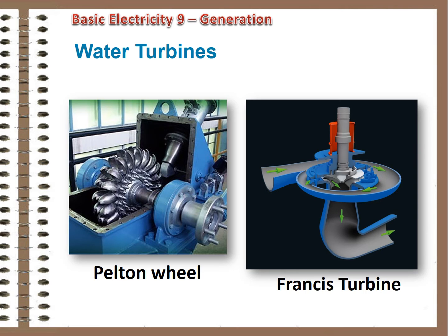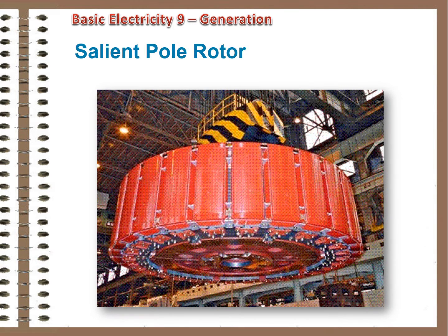Steam-powered AC had no trouble spinning magnets at high enough speeds that the cyclic nature of AC power was not visible. 50 or 60 cycles per second required a rotational speed of 3,000 or 3,600 RPM, easy for a steam turbine. Water wheels can't turn that fast. Their size and bulk made it impossible.